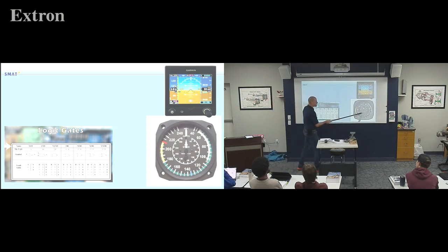So I put up an airspeed indicator. Now this is not electric, that uses air pressure, right? You haven't learned about them yet, but basically there's a ram air pressure, and depending on how high the pressure is pushing into the back of this thing, that'll be a fun class, I can't wait until we get to it, when it pushes into the bellows, the needle's going to move, and it's all based on how high the pressure is going into it.